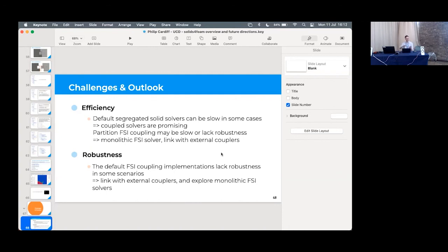Yeah, it should work. That's independent of the solid. The only thing the fluid needs from the solid is its geometry. So it gets that, and that just comes by the mesh. So you can do whatever you want with boundary conditions, give or take, except for force. Well, I'm not sure if I'm answering your question. I'm probably not understanding it fully, but we can chat afterwards if that helps.